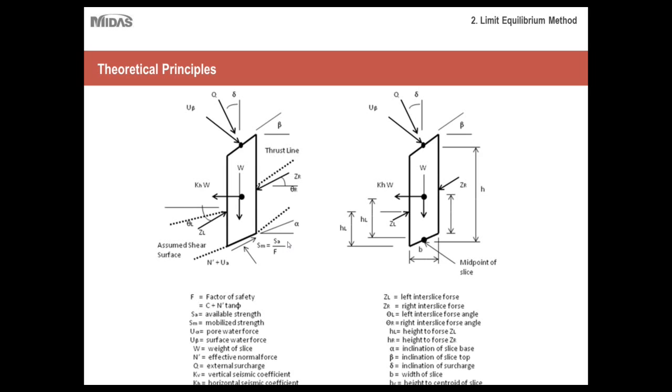Okay, so I won't go into too much detail about all the forces acting on the slices, but keep in mind that the program takes all these forces into account when calculating your factor of safety. For example, the weight of the slice itself, the normal force acting back upon it, shear forces on the bottom of the arc, as well as interslice forces in both the normal and shear direction, and any external forces acting down upon the slice itself. You can refer to this later, maybe when you're studying in your own time, just all the different forces that are being applied to your slice.